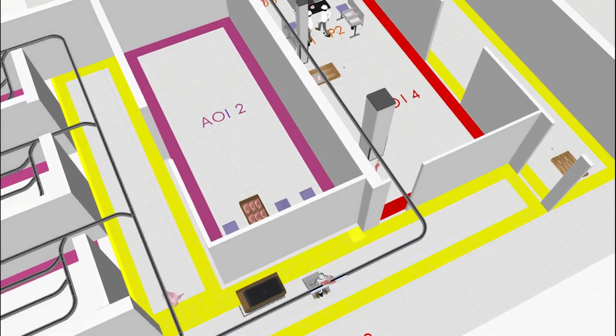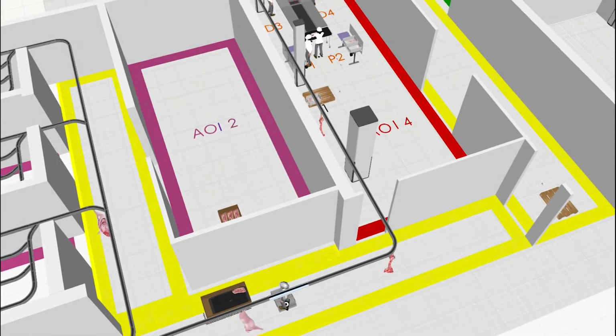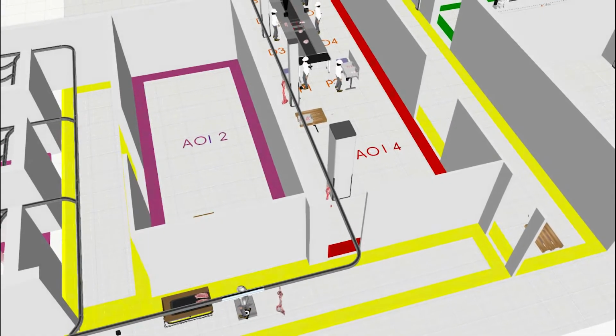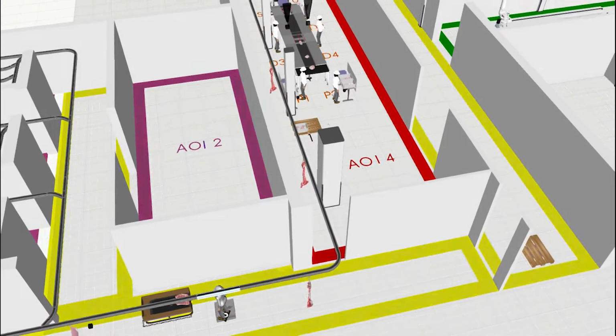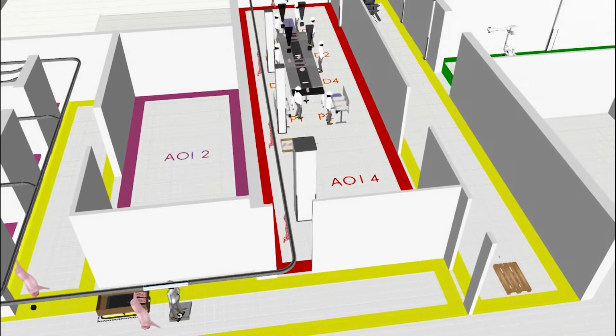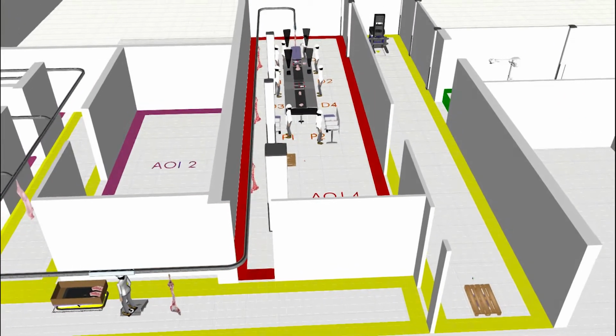Regarding the navigation method, a virtual guide path with laser navigation is proposed, because such a system requires no floor installation, which could be problematic in an abattoir with production facilities with tiled and wet floors. The proposed guide path is very simple and assumes only 2 service functions, pick-up and drop-off position.